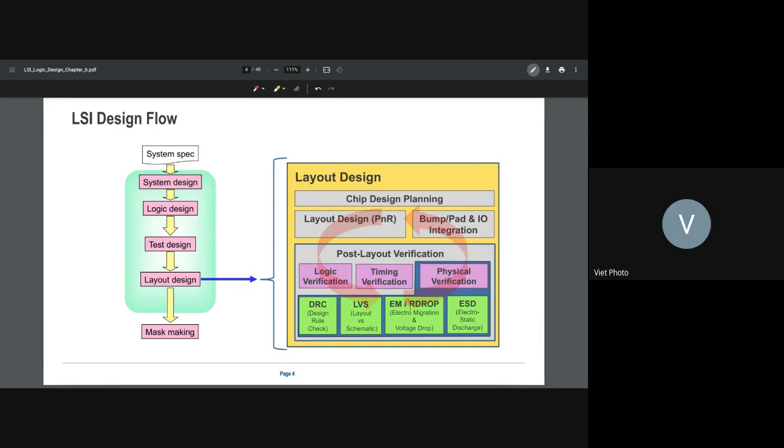The source is here, and it goes to the cell, so you have the current I going through here, and you have an R here. When you have a VDD here, then at the pin connected to the cell, because of the resistance R from here to here, the voltage drop is IR. That's what they call IR drop.